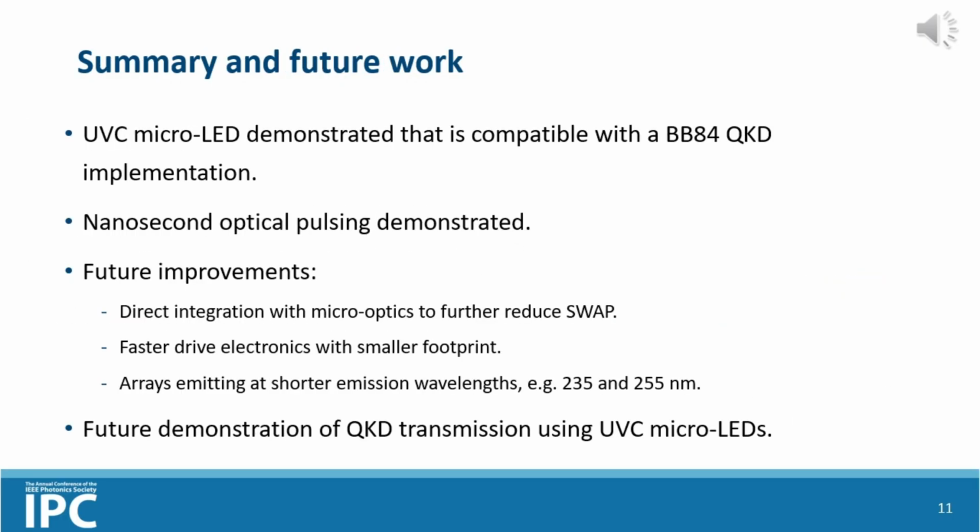So here's a short summary of this presentation and an outlook towards future work. Here we've demonstrated the design of a UVC micro-LED array that is compatible with a concept BB84 QKD system. We've demonstrated that the pixels can be individually addressed in order to deliver different output polarization states, and that nanosecond or even sub-nanosecond optical pulsing is possible.